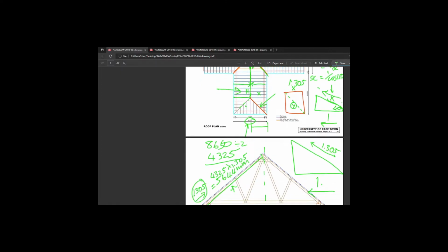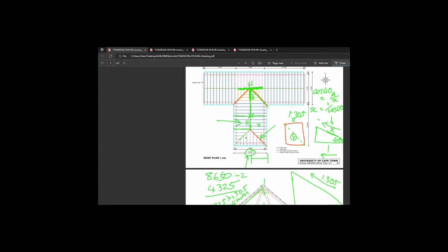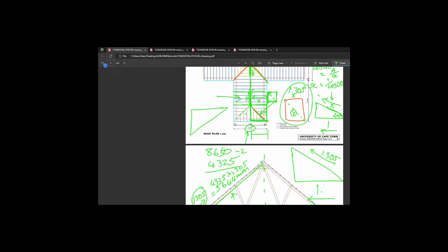That doesn't tell us this length for our hip rafter. So it's a bit easier from here, which turns out is just some Pythagoras. It's interesting, I had to wrap my head around this. Firstly, you've gone from plan, a square, okay? You applied a factor to tilt this square up to an angle. So first you had a flat square, you've tilted it up, so it faces the ridge. This end of your square is now on the ridge, okay? But you only want half, you want that dissecting line through your square. And so you apply Pythagoras.